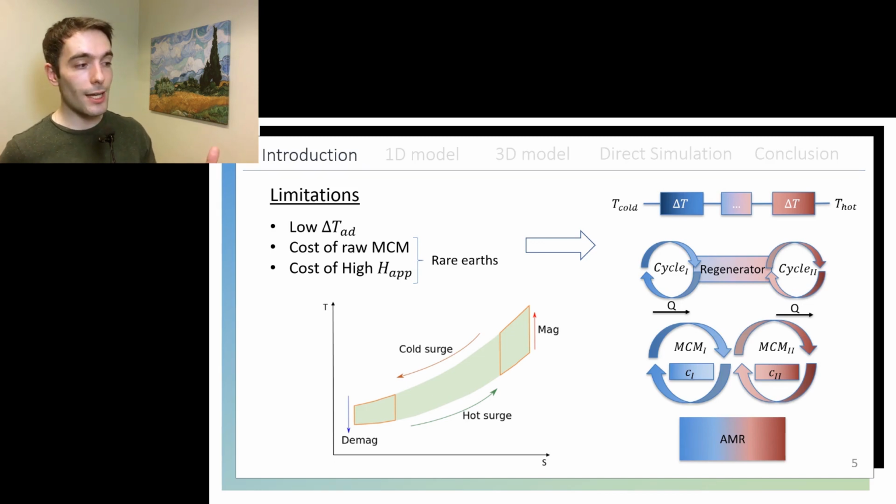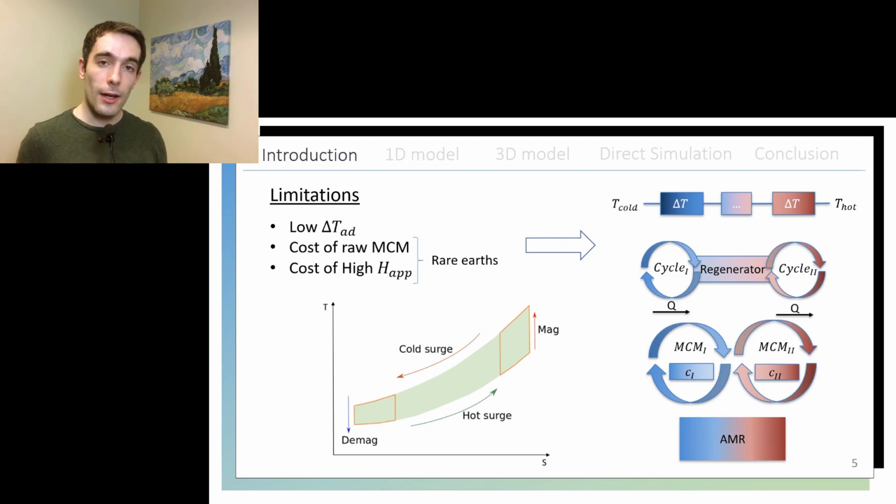And in our specific case, the magnetocaloric material is at the same time the refrigerant and the regenerator. That's why we call these devices Active Magnetic Regenerators, or AMR for short. So the regenerator has the magnetocaloric material arranged in a porous structure, and in steady state operation, it represents a temperature span between the cold side and hot side of the machine. And it is in this temperature span where we see blurred all the thermodynamic cycles together.